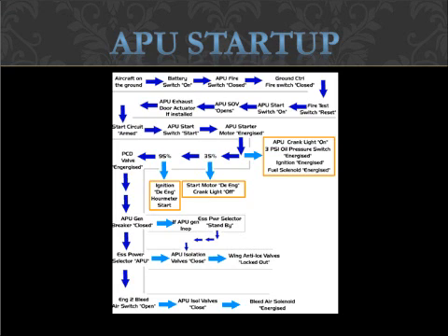For the majority of aircraft with an APU installed, air is used to start the main engines. This air can come from either the bleed air section of the APU, which is just downstream of the compressor, or from a load compressor attached to the front of the APU. Either bleed air or load compressor air is sent to the main engine and used to turn an air turbine starter, not direct injection to the turbine section. The air turbine starter, like any other starter, drives a gear train to spool up the main engine.